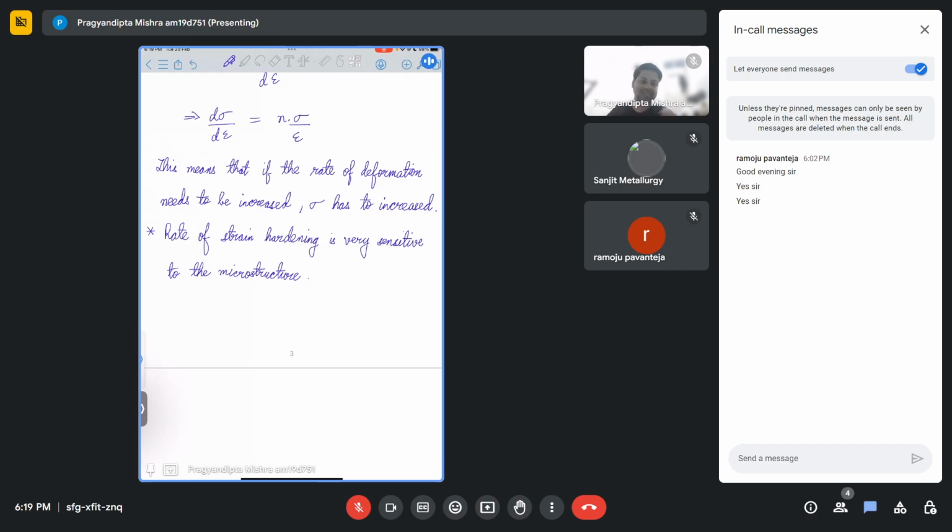Depending on how the stress strain curve lies, you can see where your rate of strain hardening will be changing. So essentially, for the same material system, depending on how you are processing it influences your rate of strain hardening, because the microstructure in effect will change depending on what kind of processing technique is being used. Okay, so this is something that you have to keep in mind.